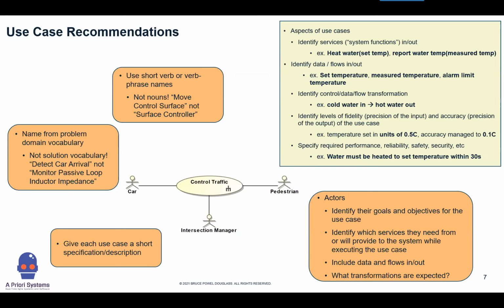You also need to, as part of your quality of service requirements, specify precision, fidelity, and accuracy. Really quickly, precision is the degree of information with which something is represented. Accuracy is the conformance to a level of precision. And fidelity is the degree of control exercised over some control value, such as an input.